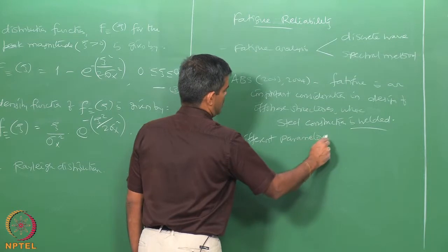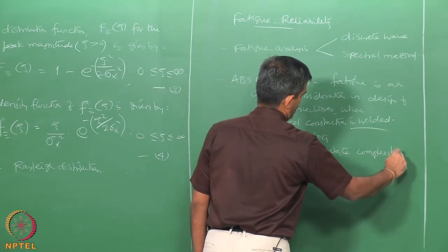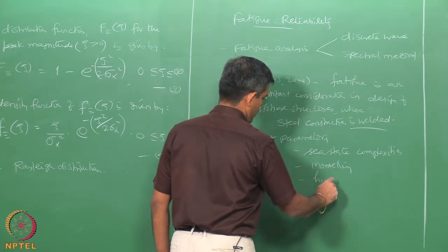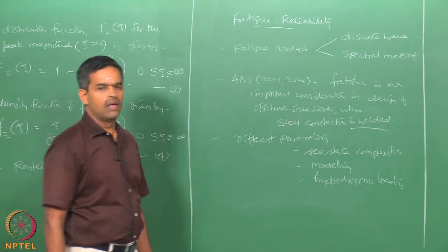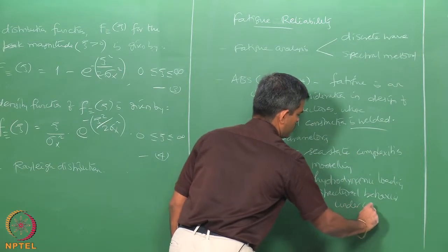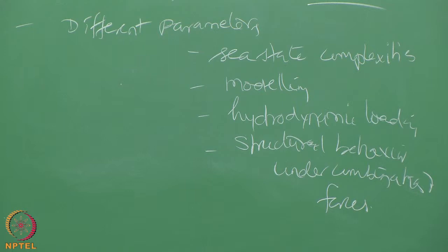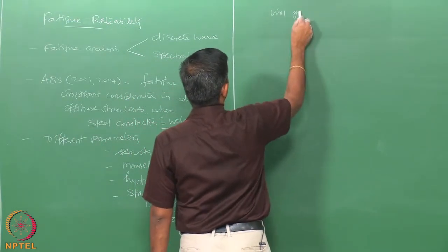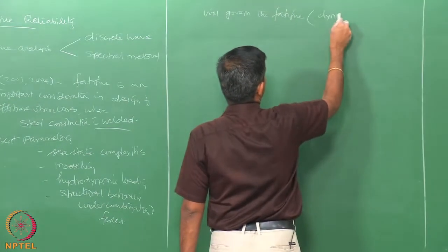Different parameters, for example, sea state complexities, complexities involved in modeling hydrodynamic loading, and structural behavior under combination of forces, will govern the fatigue failure, especially when you look for the dynamic response behavior.